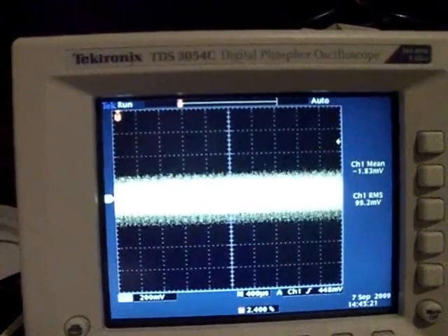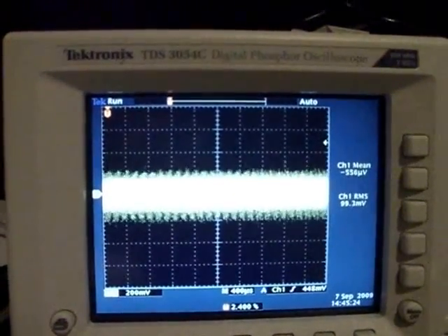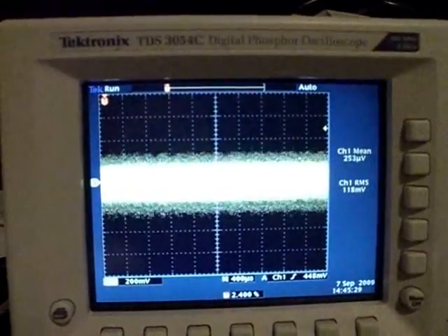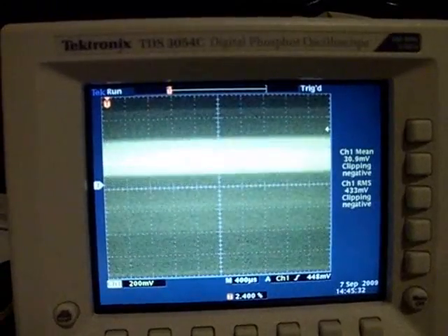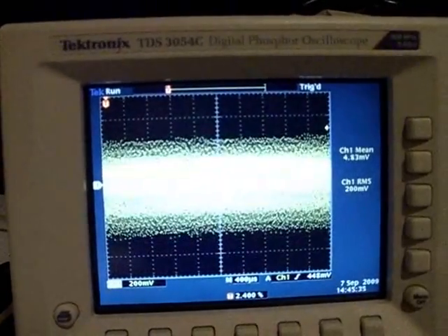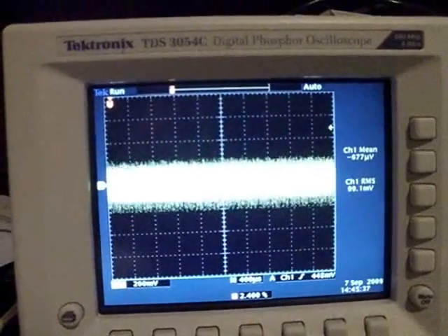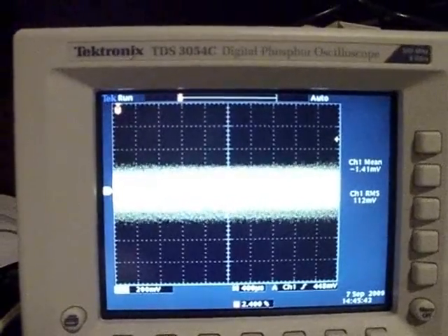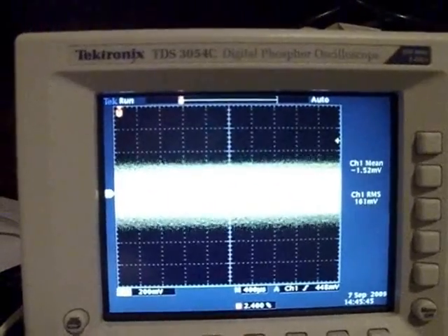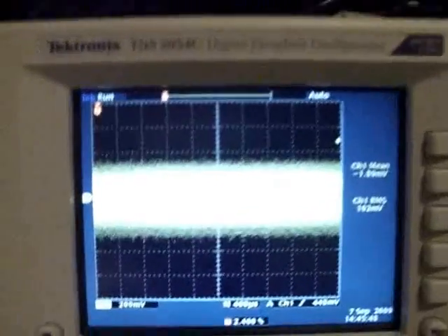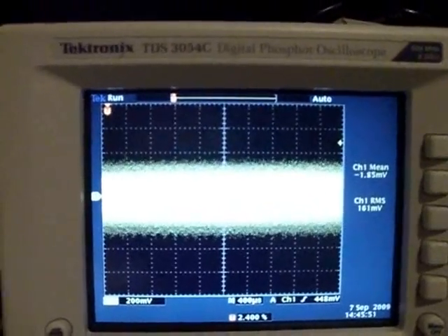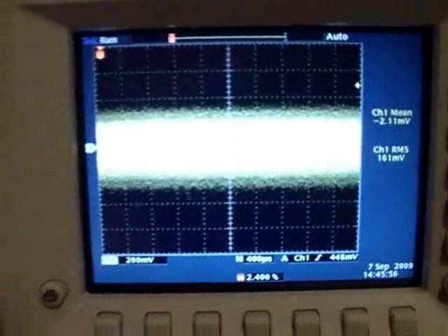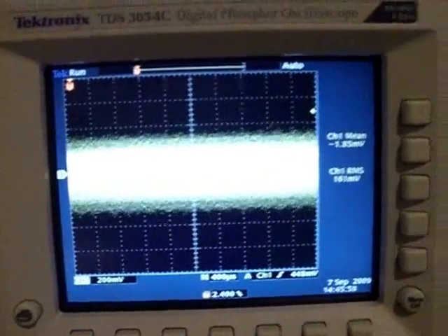You can find them with virtually any pot, even the potentiometer controlling the power supply to the 555. If you're using one of those, you can find those zones. So it's maximum on time. I'm going to reduce on time, reducing, and you would expect the amplitude to get smaller. I'm reducing, but now the amplitude is increasing, and then it's shrinking. So at that point right there is a maximum amplitude for the on time. It's in that nonlinear zone right there. So anyway, just something to play around with.